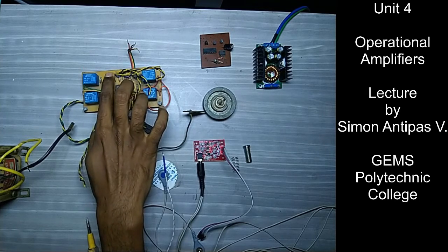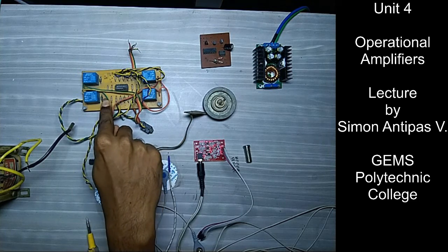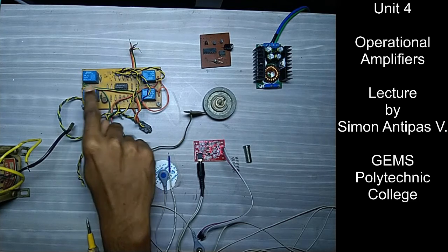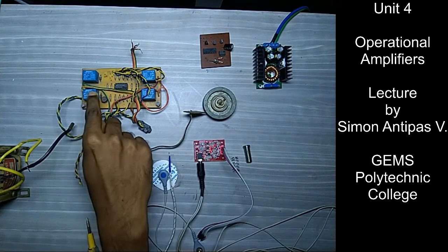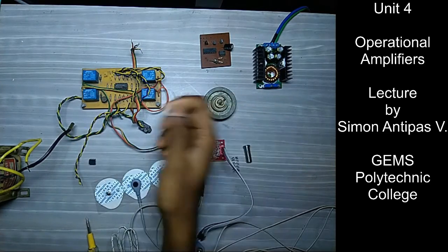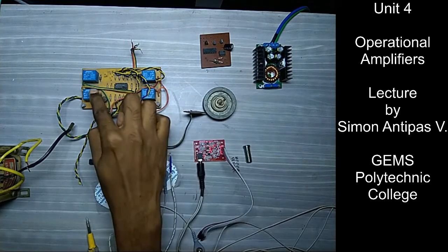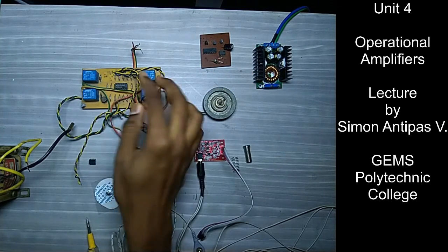I actually had one more, which I removed and desoldered for another project. So this op amp output goes to your metal cap transistor. This transistor drives your relay, and this relay is what is used as a logic input for your PLC maybe, or another microcontroller, or maybe even directly drive a logic controller for a pump. So this is how we could use an op amp.